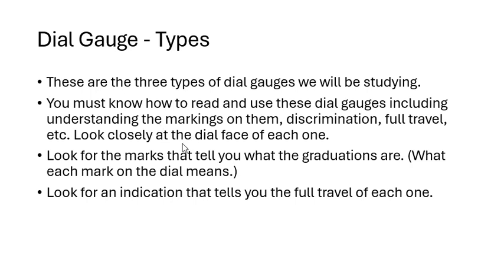Of course, you will definitely look at your reading in your dial indicator, which is your dial face, because the scales are inside of it. And if you have noticed, we have 2 different scales in there. One big, going in a counterclockwise direction, and the other one going in a different direction, clockwise. So you have a clockwise direction for the big dial and a counterclockwise direction for the little dial. And we're going to observe all these dials and read our readings.